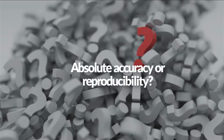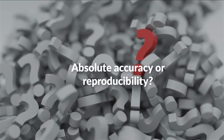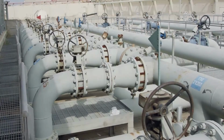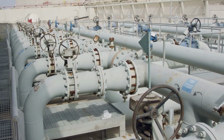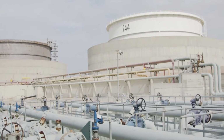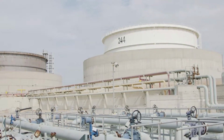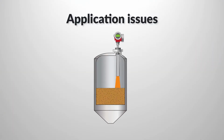Another important consideration is whether you require absolute accuracy or just reproducibility. High absolute accuracy is usually needed for custody transfer. On the other hand, for in-process applications where the target is stability for process control, it's enough that the measurement be precise and repeatable. There are other considerations that often guide engineers to suitable technology.